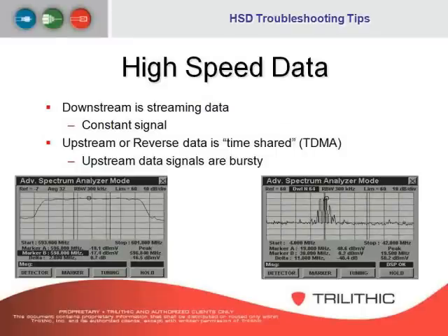The upstream data is time shared. It's called TDMA, which is time division multiple access. Upstream data carriers are bursty, unlike the downstream. Because of the bursty nature of upstream data carriers, you have to use certain tools to make measurements accurately on the upstream carriers.